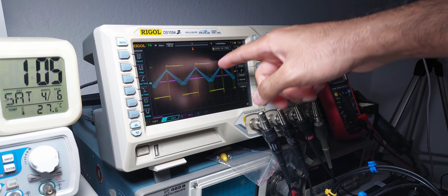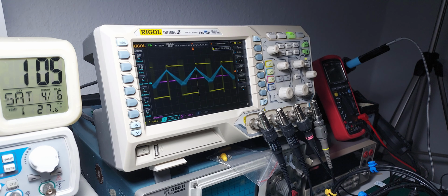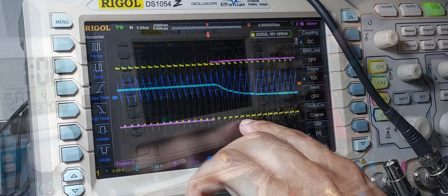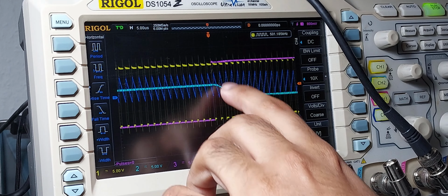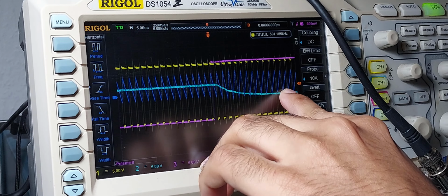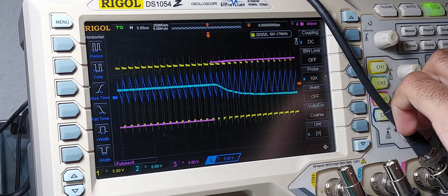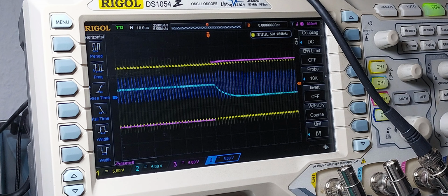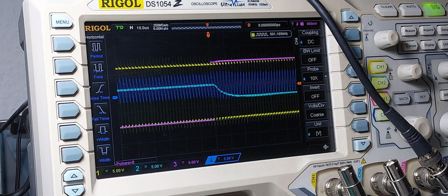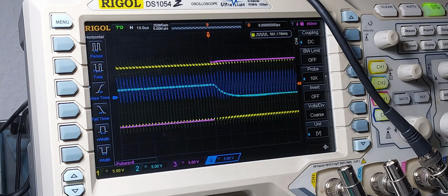this might have. This might also explain why the coarse ADC is so fast despite the modulation frequency only being 500 kHz. The integrator slope could be calculated in real time, and the period adjusted accordingly to make sure the integrator does not exceed a limit. The integrator response with a stepped input contradicts this, however, as the integrator peak-to-peak swing increases as expected as the input passes through 0. The cyan trace, which is the output of the AC feed-forward circuit, shows how it prevents a fast step from disturbing the integrator's balance, essentially bandwidth limiting the input.